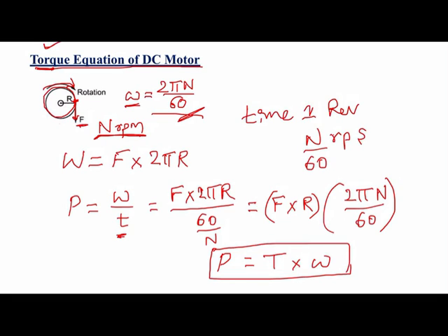The same concept is applied to the DC motor, which takes electrical energy as input and gives mechanical energy as output. The mechanical energy is tapped at the rotor part connected to the shaft. The shaft is rotating, that is the mechanical energy. Since there is a rotation, there exists a torque, because torque means the twisting or turning force about an axis.